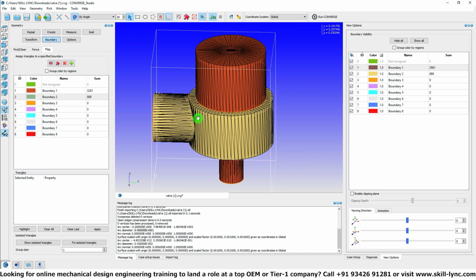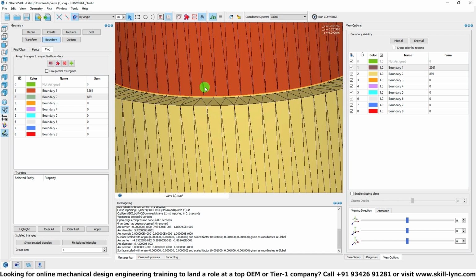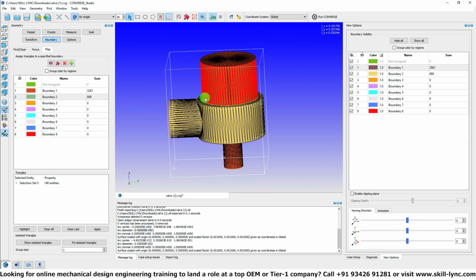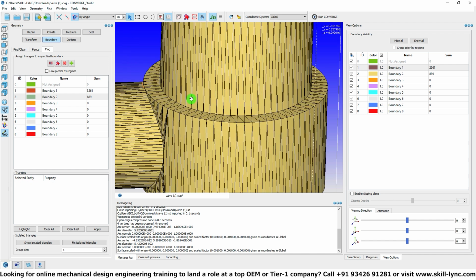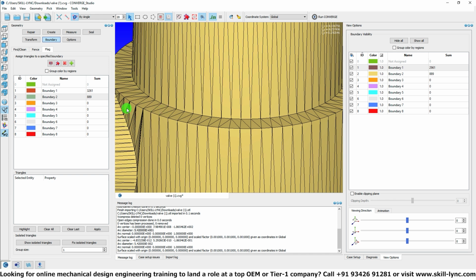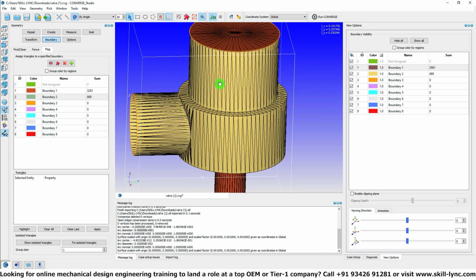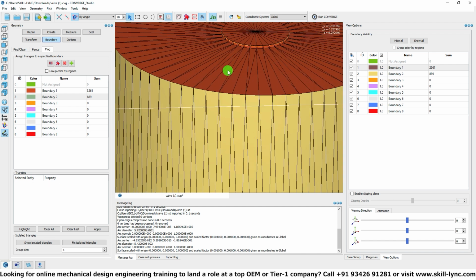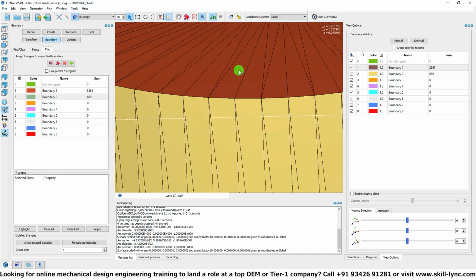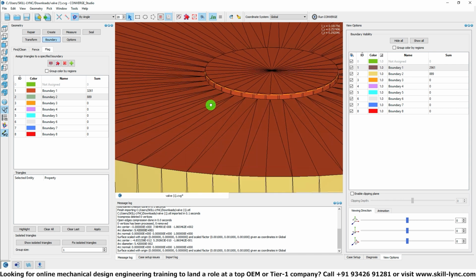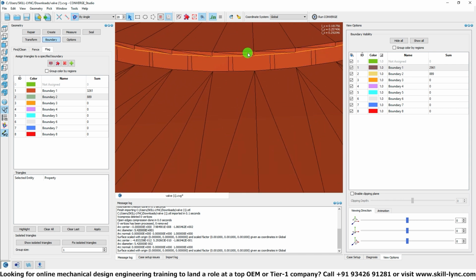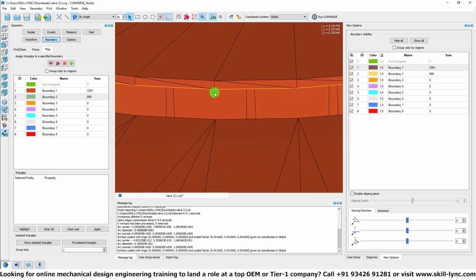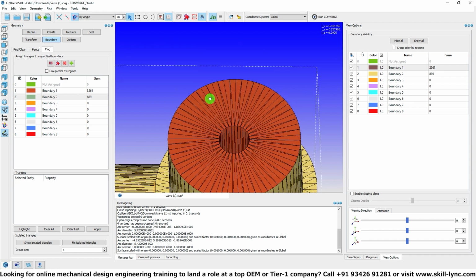Okay, and coming to the top, what I'm going to do is I'm going to click on this guy and delete that, because that is something that I won't need. And as you're deleting, you will see that the inner volume would be made up of perfectly connected components. So that also gives you a clue, which means this can go directly. And here you can see that perfect connections are made, and something weird is happening here. So we'll get to this component, but this part that is attached with the open edge, that basically belongs to the solid, so you can delete that, right?